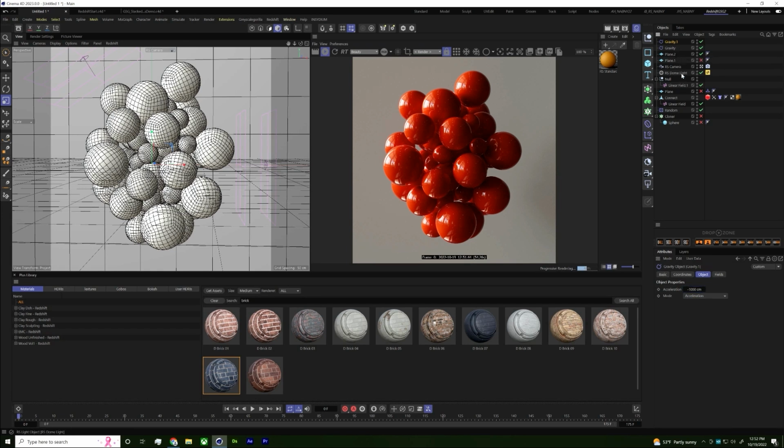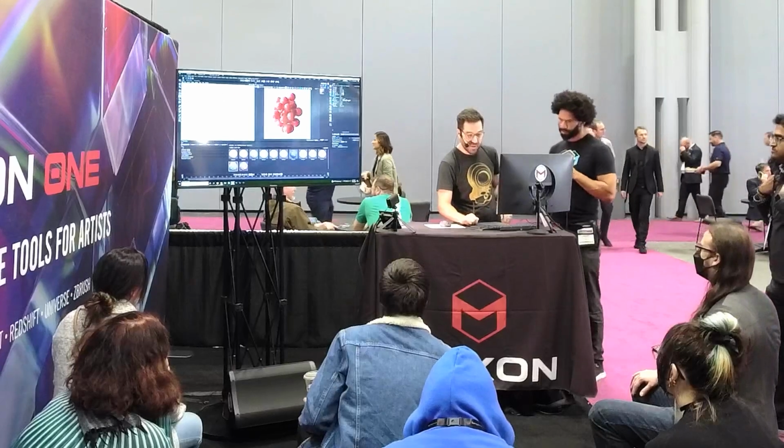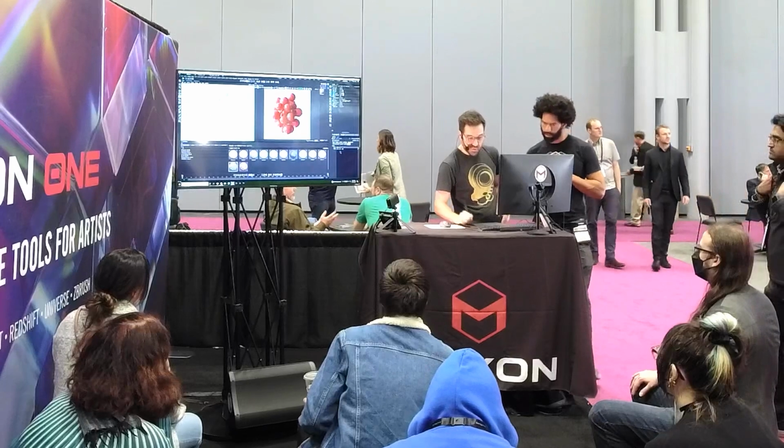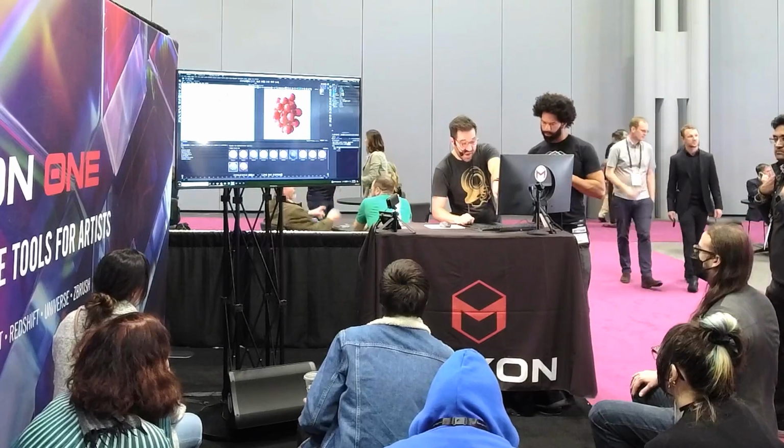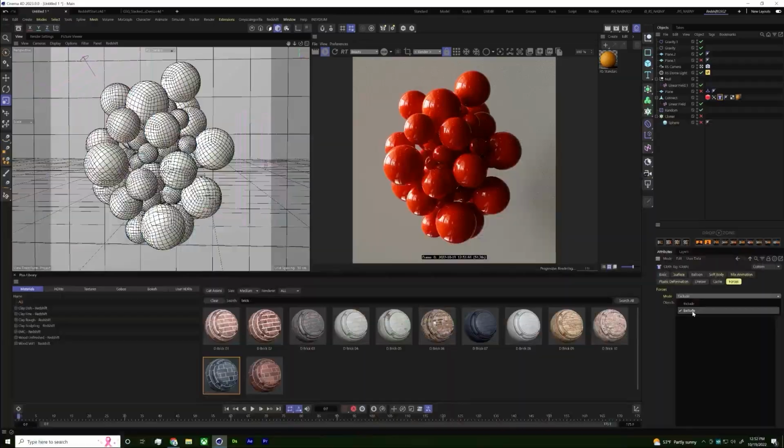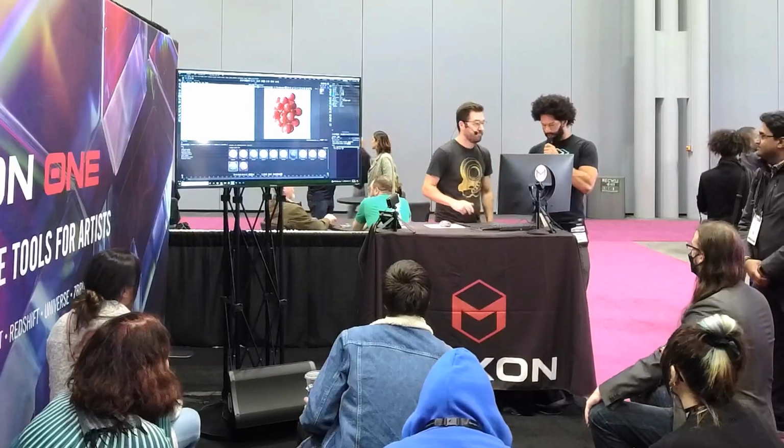You essentially use separate gravities and you use the Forces tab to control what is excluded. See how exclude is turned on? You can include and exclude different ones. By default, they're all included. What you would do here is say, okay, I only want to include the ones I pull in, and then pull in gravity and anything else that you have. Thanks for the question. That was a good one.